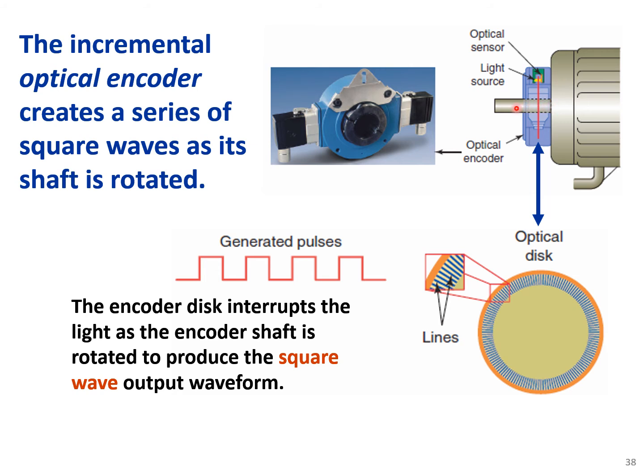Here we only have one optical encoder. And what is that optical encoder? There is one disc. That disc is connected to the rotor and rotates with the speed of the rotor. On the disc we have some lines, and there is the optical source, or the light source, and every time each line or slot passes,